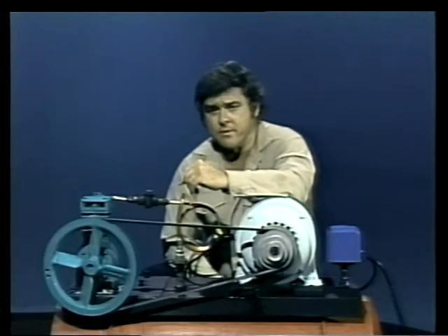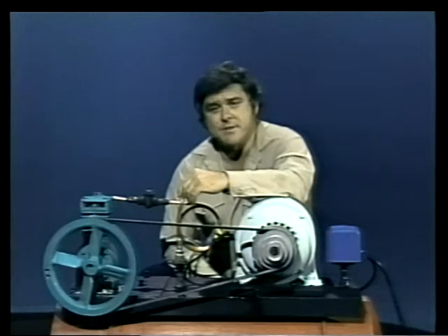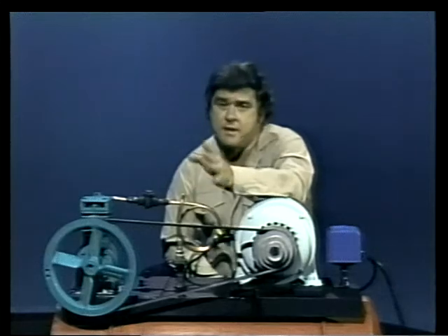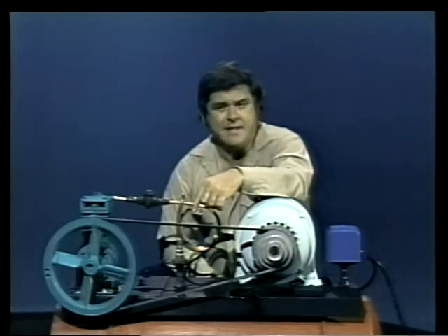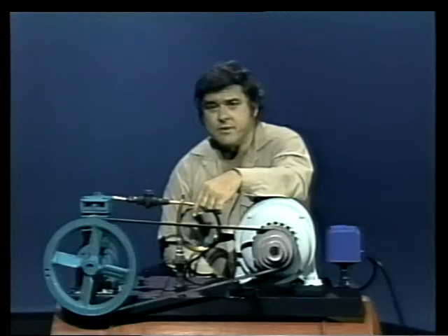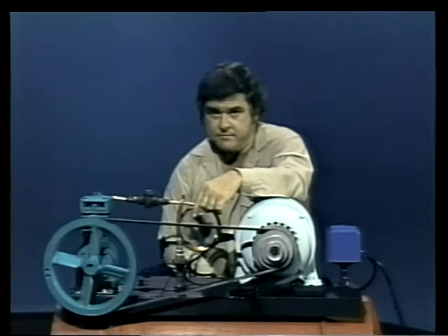To this point in the program, we've been talking about how compressors work. We've seen 7 different types. First, we looked at positive displacement compressors: reciprocating, rotary screw, sliding vane, liquid ring, and the rotary blower. In the last section, we saw the 2 types of dynamic compressors: centrifugal and axial.